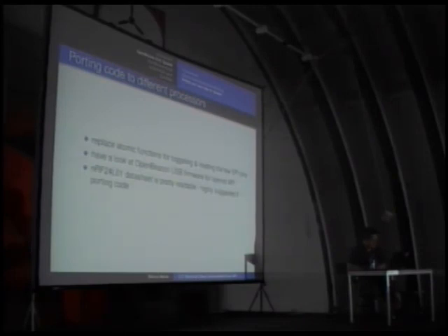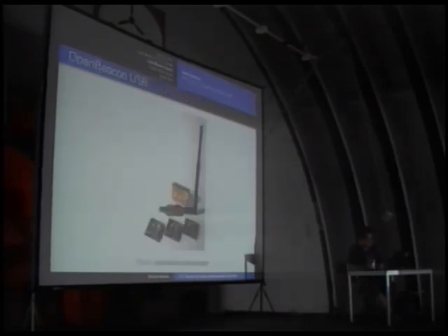And if you have a bigger processor, then have a look at the OpenBeacon USB firmware, because there you have a layered API. And if you want to work with either OpenBeacon USB or the CCC Sputnik, you definitely have to read the nRF datasheet, which, if you compare it to other datasheets, is pretty verbose.